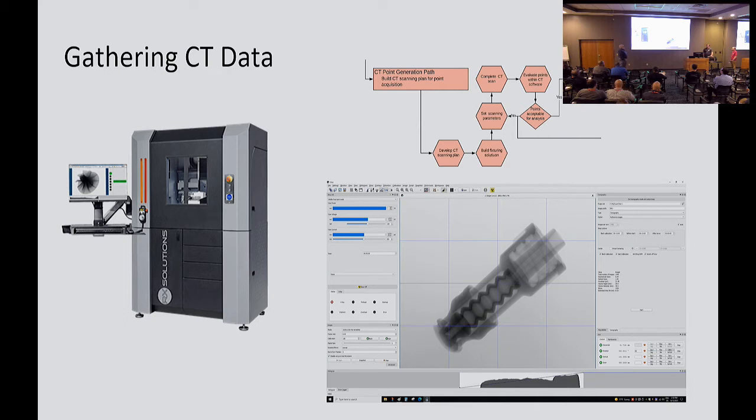And if anybody has dealt with these scanning systems, that's as much bad as it is good. Because when you measure with your CMM, in essence, you own every point. So if I measure a bore on my CMM with 17 points, I cheerfully own 17 points. If one point is screwing me up, I can come back and deal with that point. If I own 10 million points, that's a lot of ownership. Now, where's the bad data? I don't know. I can't even go back and replicate it with a CMM. I can't say, hey, go back and retake that point. With CT, I just got millions of points.